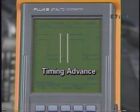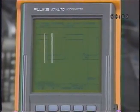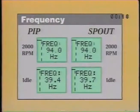You can see the increase in the timing advance, much greater than at idle speed. The falling edge of the spout pulse is much closer to the pip's falling edge, indicating a longer dwell and increasing coil saturation. Both of these conditions are just what you'd expect when comparing the timing advance and dwell at idle to 2,000 RPM. You can follow the same procedures as before for measuring frequency and the percentage of pulse width. As you might expect, frequency should be almost identical for both pip and spout, but considerably higher than at idle.